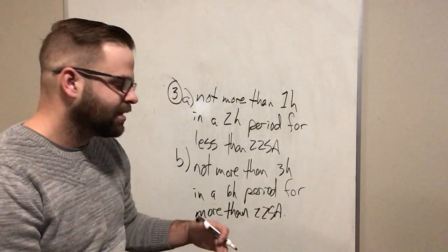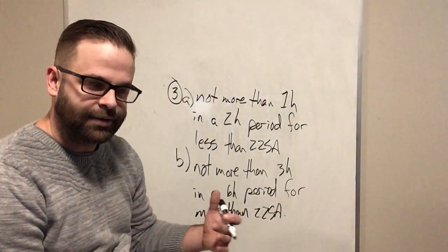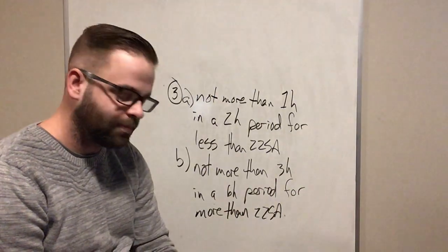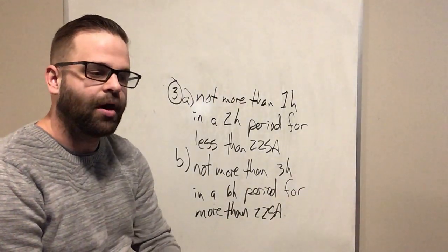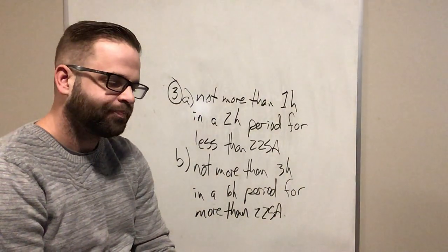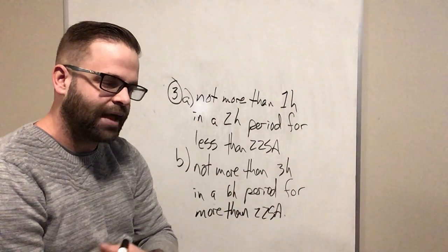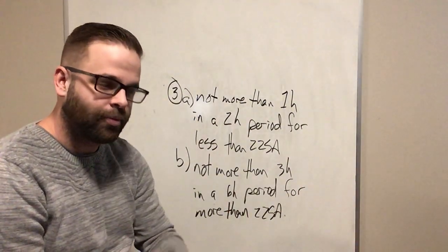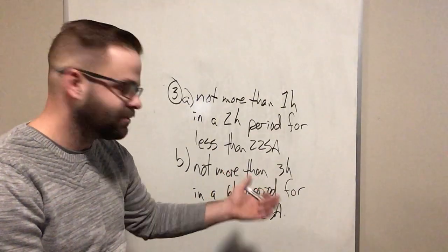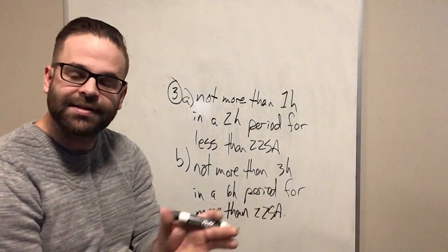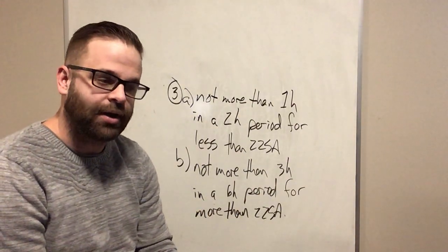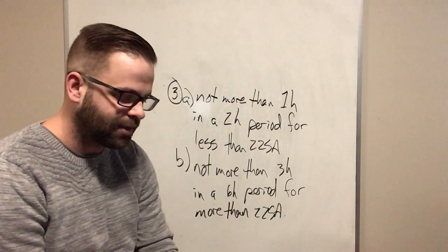So hopefully that makes sense. You'll hear it more in advanced, but you've probably heard a little bit: it's duty cycle. How often is it going to operate? The main idea is that if that circuit is basically going to operate less than 50% of the time during a set window, then it can be classed as a non-continuous load rather than a full continuous load.